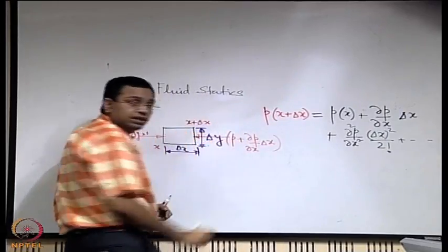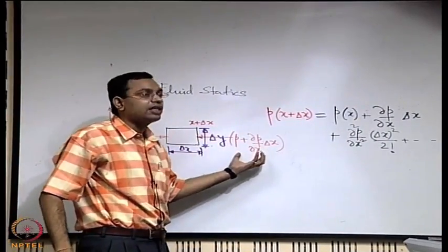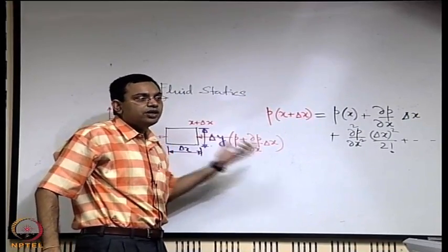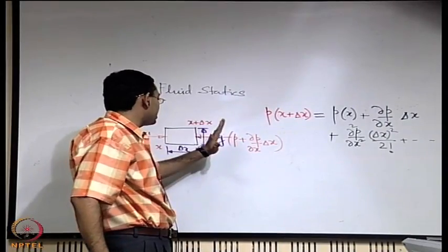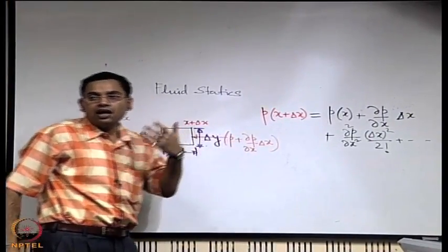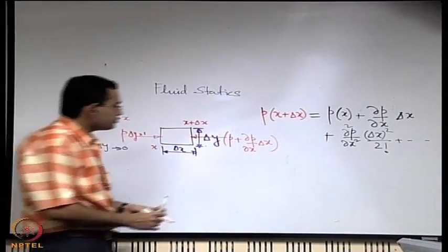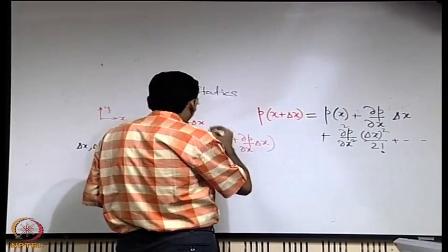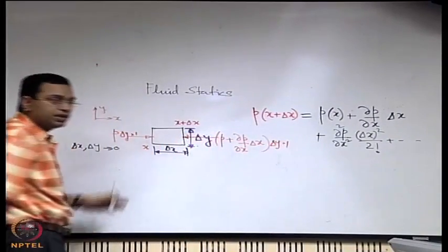that will be the pressure here. We will keep this in mind. So later on, whenever we encounter any function, we will use the Taylor series expansion to identify the change taking place across different faces of fluid elements, because we will have to do that very commonly in many of our analyses. So this, multiplied by the area on which it is acting, is the force due to pressure on this face.